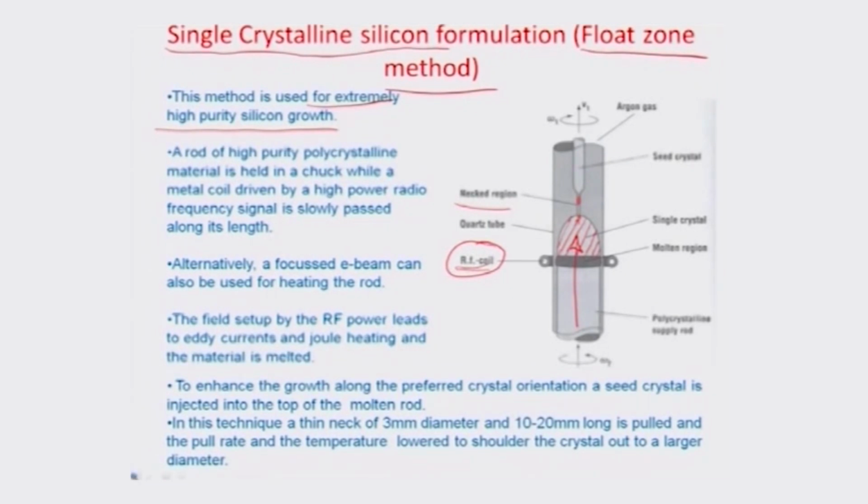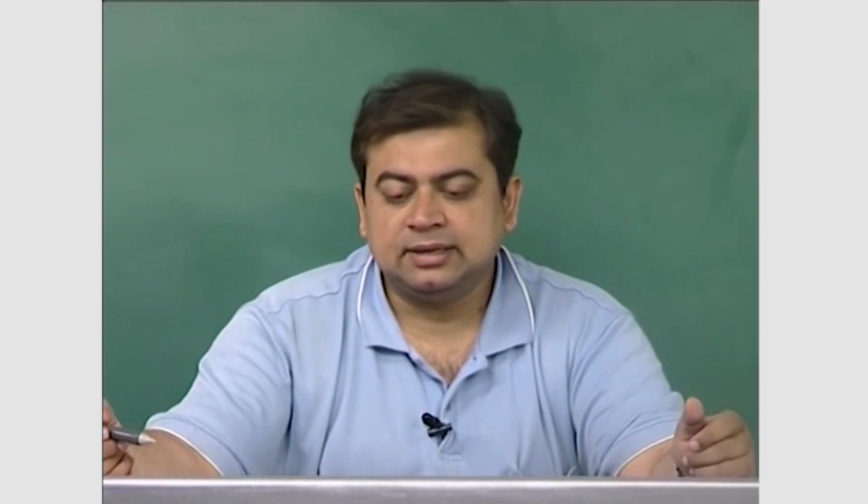So, the other material of importance to microsystems fabrication, as has been indicated, is glass. And glass is actually chemically silicon oxide, and the content of silicon oxide, however, varies in different glasses. For example, soda lime glass would contain about 68% of silicon oxide. Borosilicate, another variety of glass, would contain about 81%. And the highest and the purest form of glass is quartz. Really, it's fused silica, which is actually 100% silicon oxide.